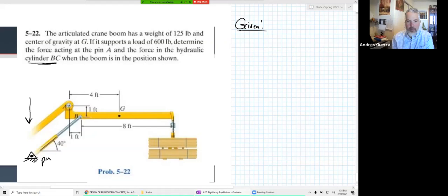Now, as our problems get more complicated, I found one way to draw things nicely and have the relative locations of things show up at the right spot is to first draw our points. Instead of going right in and drawing the physical objects, what if point A was right here? Well, that puts point B maybe right there. We can put a point G at about right there. And then what if we put the load at about that spot right there? Now we can draw this whole thing as one solid rigid object right there, and it captures all those points.